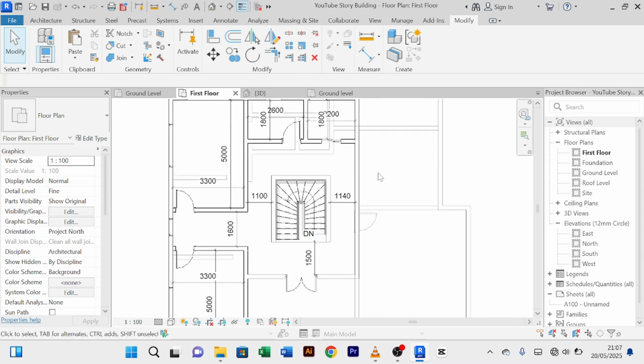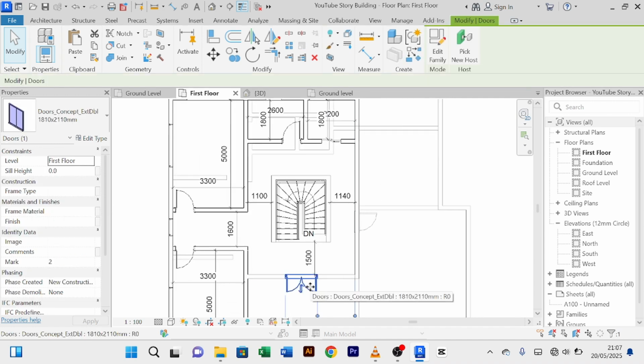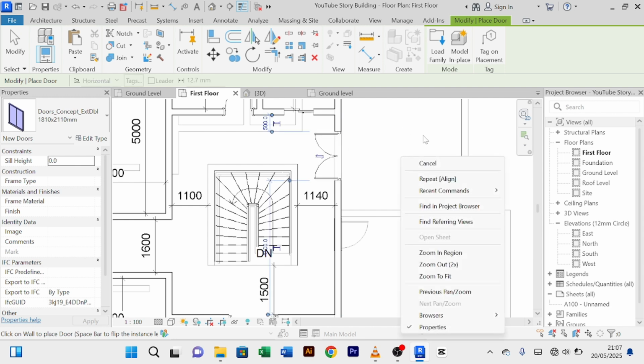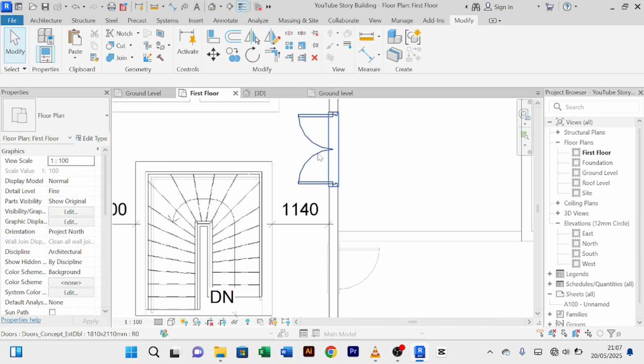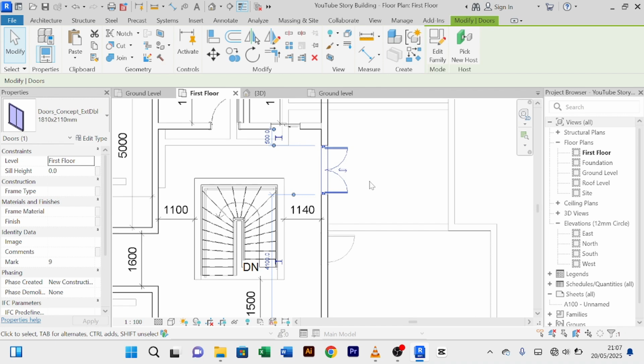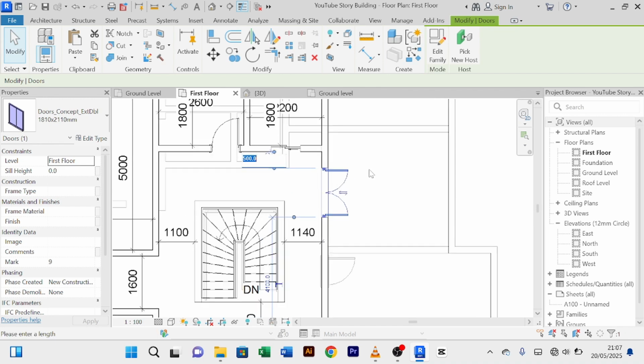So I am going to use this exterior door. I'll say create similar, and I'll place it around here. Then it has to open outward, and this distance is a lot. Let me say 300.